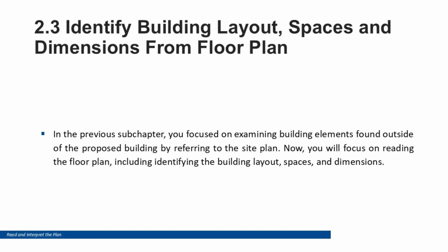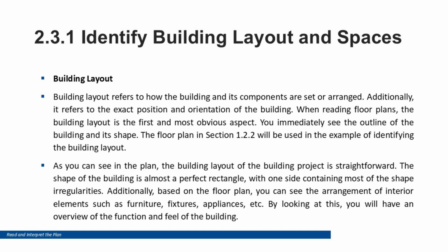Reading floor plans. A floor plan represents a horizontal slice of the building, typically cut at around 1 meter above floor level. Floor plans show room layouts and names, internal and external walls, door and window placements, stairs, cabinetry and fixtures, dimensions for walls, rooms, and structural elements, notes about materials and finishes.